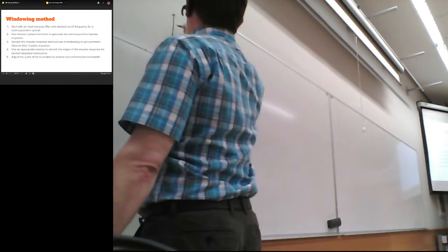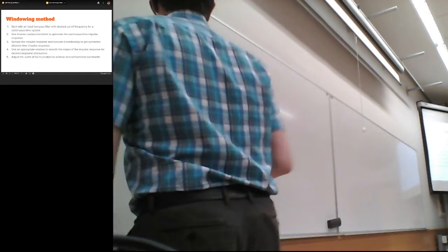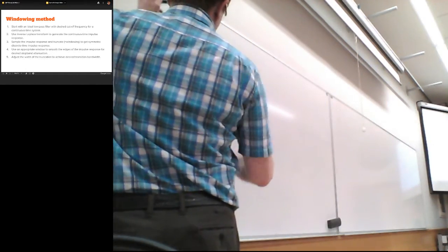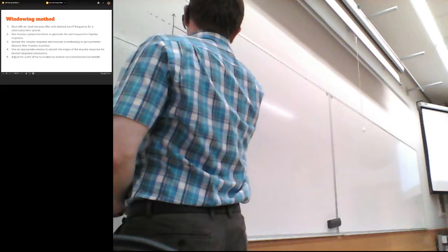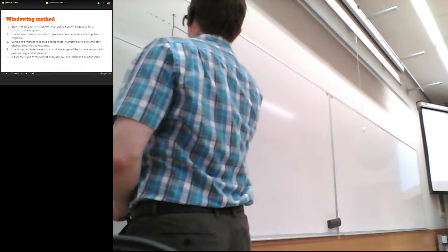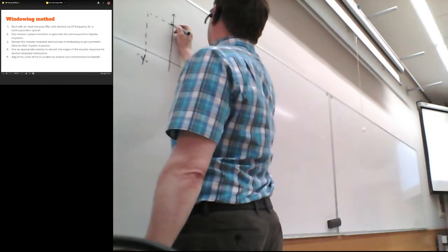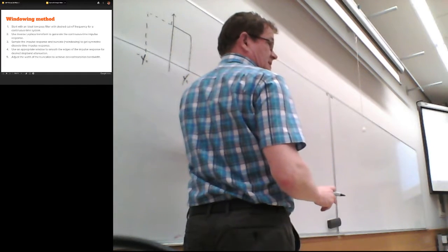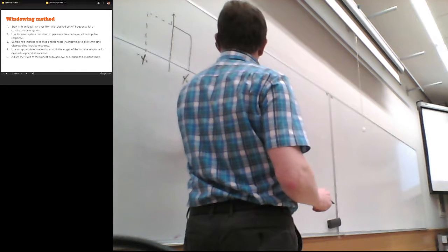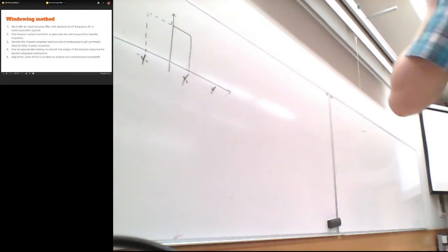So frequency F, you have the cut-off frequency of Fc and on the left-hand side minus Fc. Well, this would be ideal. You have a box-shaped filter, meaning that on the pass band it passes everything. Then on the stop band it attenuates everything. So nothing gets out on this frequency range, and everything gets out of the system on that one. So that's the ideal case.